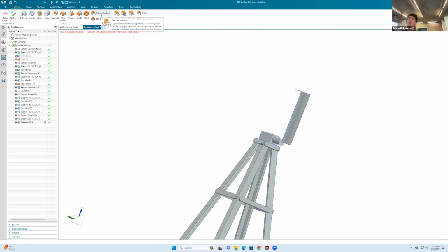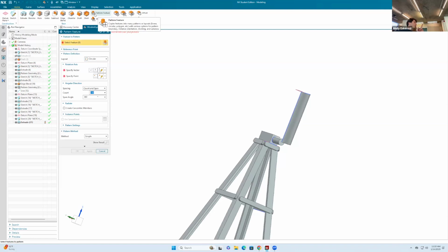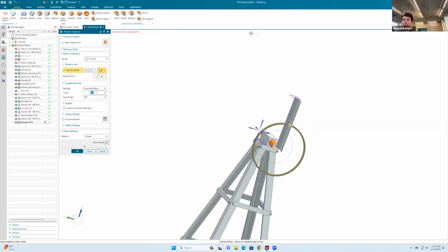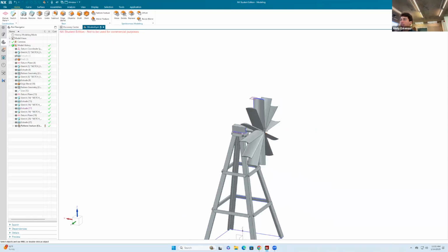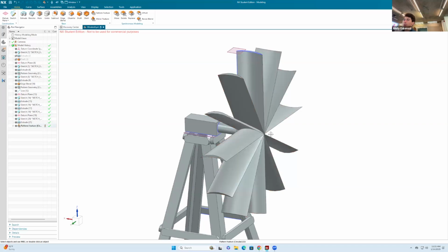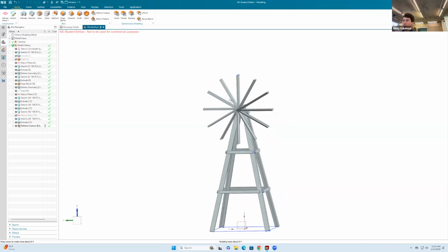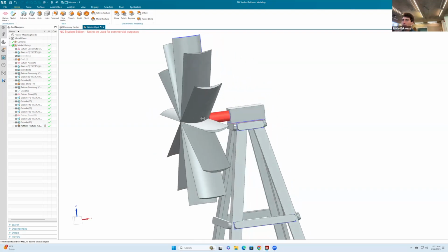And then you go back to pattern. So this is where you would use the pattern feature instead of, like you were asking the question before, geometry pattern, because I want all of these to eventually be the same figure. So feature pattern, I will select that feature and then the vector, this guy in there. So this is a lot. We probably want like 12 of these instead, and I click on OK. So now you have this, but again, it looks kind of ugly right here. We're gonna fix that in just a second, and we can always modify this in a moment.